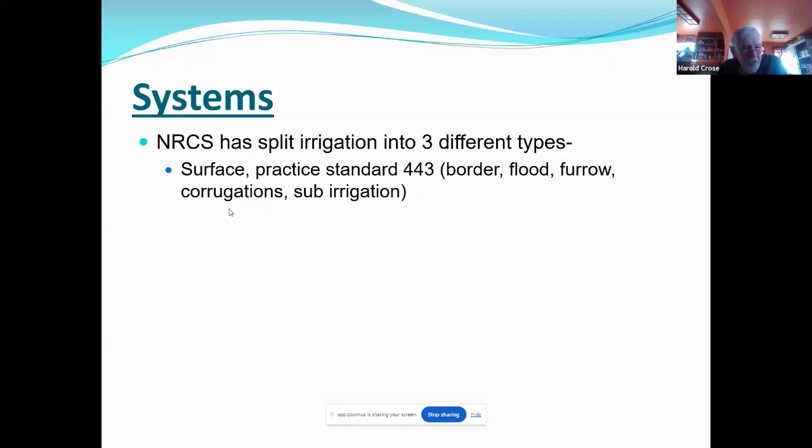Well, in the Columbia Basin, a lot of the crops that we grow, many seed crops, do not do well under sprinkler irrigation for pollination reasons primarily and during seed set periods. So we like to maintain surface irrigation where you can, as long as it's according to an irrigation water management plan, and you're controlling erosion as well.